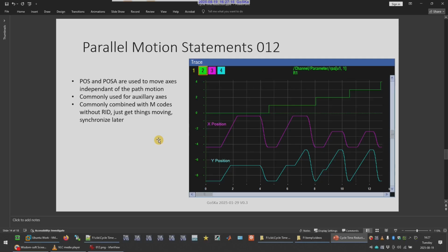And this is something that you as a builder have to know. It's your machine, it's your mechanics. Same thing with complex end effectors. There's a lot of times where we just need to get things moving, and we'll be resetting our end effector between different points on the part. Like we'll be doing all this reset and retract stuff while we're moving between holes. That's very, very common. Again, this is for the machines where that extra 30 milliseconds somewhere means something.